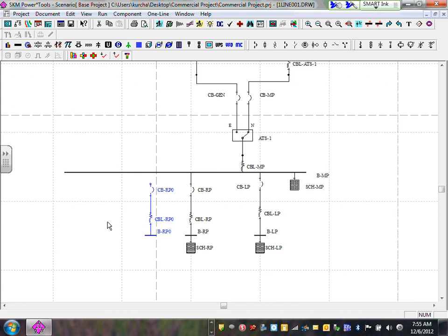Okay, now, is it still blue like this? Is yours still blue? Were we copying the panels too, or just? No, we don't want the panel, because it's not a panel. We're just copying a branch circuit, guys. We're going to add a motor to that bus. You're going to see in a second, we're going to add a motor. If it's still highlighted like this, by the way, gray means it's not connected to the system. It's not going to get juice.